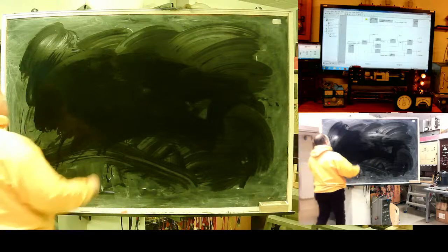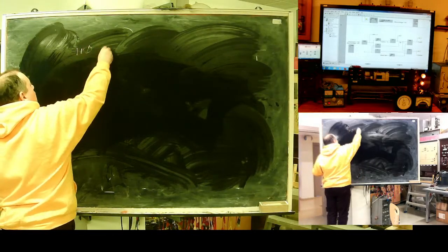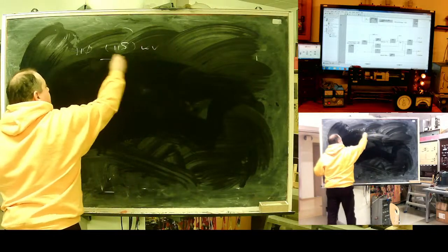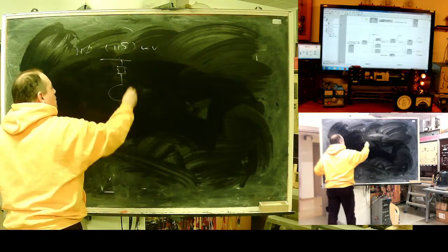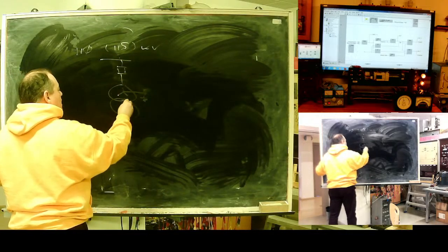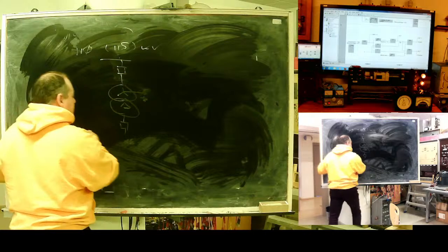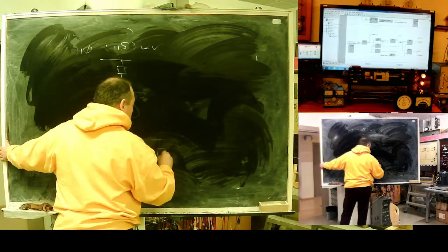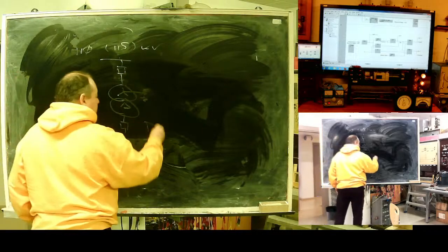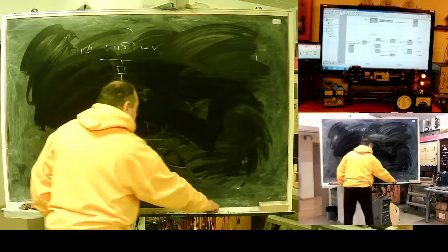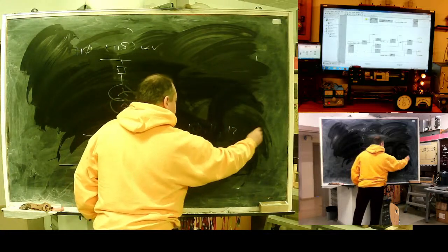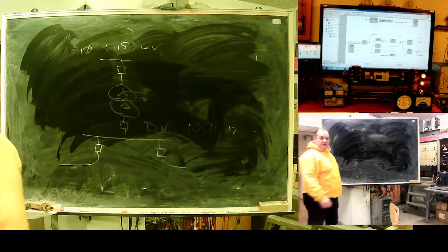What's the basic? You have a 110 or 115 kilovolt network. You have your substation, here should be a star, a delta, powering your distribution network. I don't know, it can be 10, 11, 12, name it, 24, 35 kilovolts.